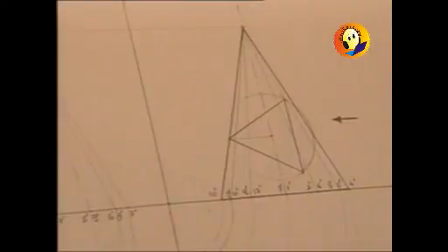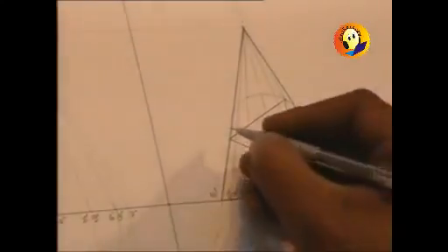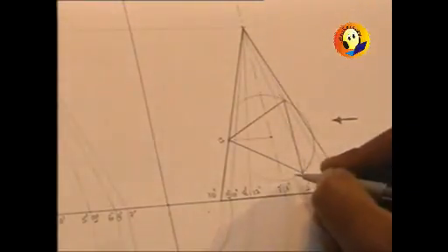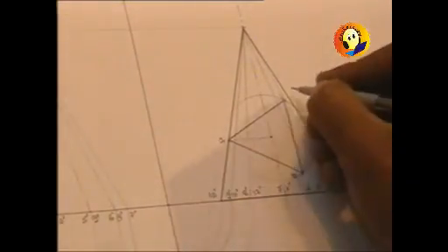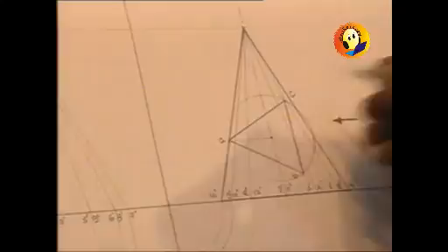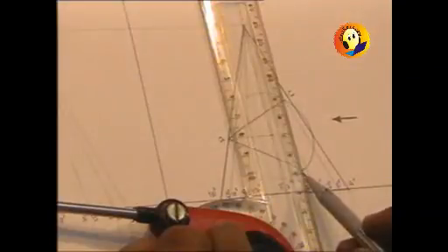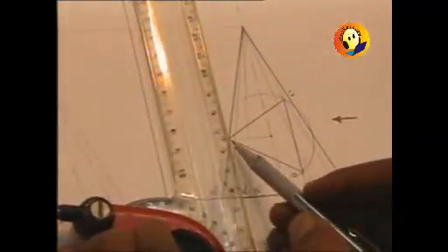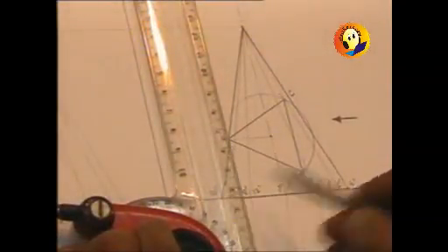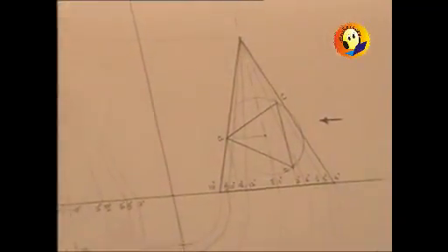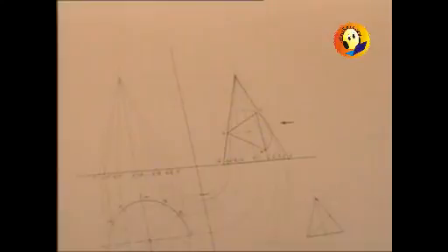And then from the side view we will name the corners of that triangular prism as A, B and C, and those points should be taken to the top view. So we will have to simply draw the projectors through them, and then through rotation we are required to take all these points to the top view.